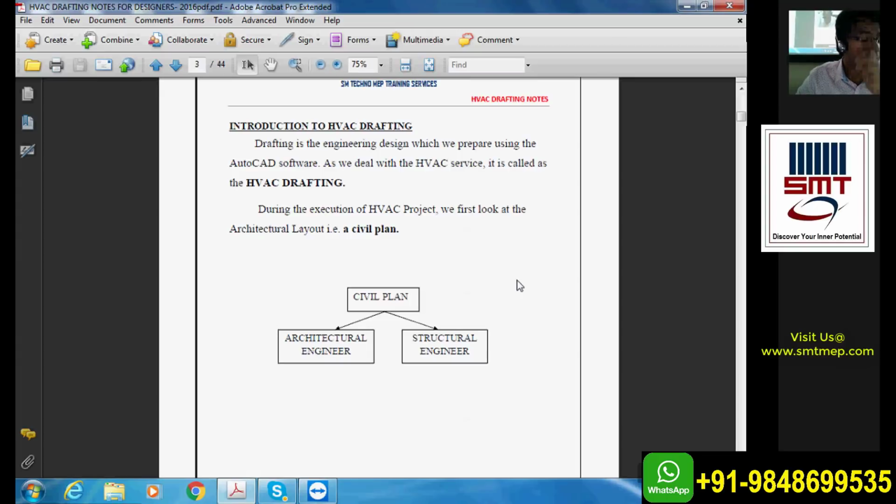Normally, until now in the course that you people have come across, which module is going on? Second module has started, ended, going on, right? So you all know the parameters on how to do the duct designing, right? You have a velocity regain method, you have an equal friction method, then you have come across the different names and nomenclature of air terminals, all right, diffusers and grills, right? So like that you'll be getting registers and different kinds of volume control dampers to control the volume, etc.